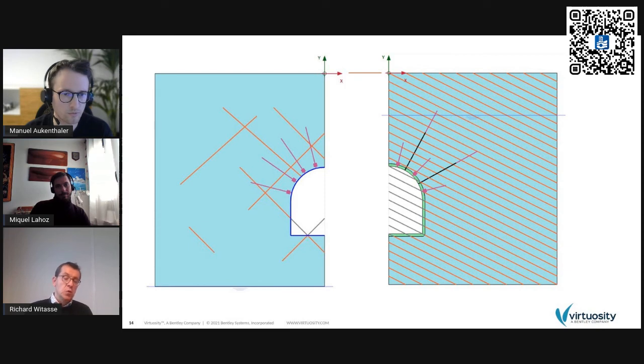Next to that, in case we are considering free lengths of those elements, we can simply use the node-to-node anchor. The node-to-node anchor in PLAXIS is the simplest element one could think about. It's simply a uniform, linear, unidirectional spring, which is represented on the right-hand side by the black line, and which could be connected to an embedded beam. The embedded beam then represents the grouted length of the anchor. So this is, very briefly, the type of elements that we can use in PLAXIS for modeling support and reinforcement.